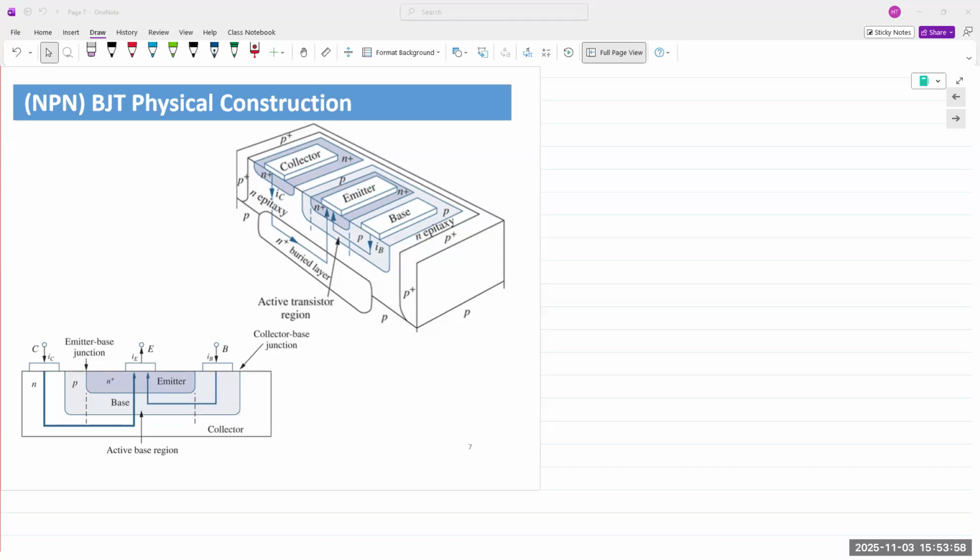All right, then let's talk about how and why this functions and how the design influences the collector. So let's say we have this NPN transistor, right? In this NPN transistor, what happens if you forward bias the collector and the base? It's an NPN transistor. So you have a P-type base structure in the middle, and you have an N-type on the collector. So let's say what happens if you forward bias. Sorry, not forward bias the collector. If you forward bias the emitter and the base.